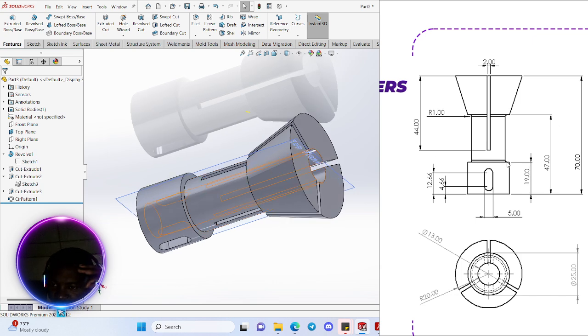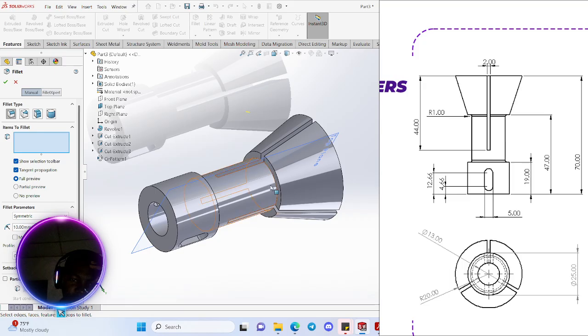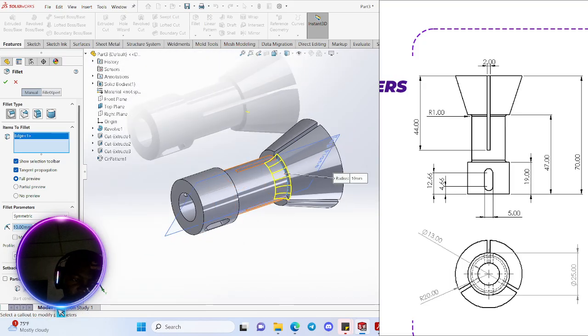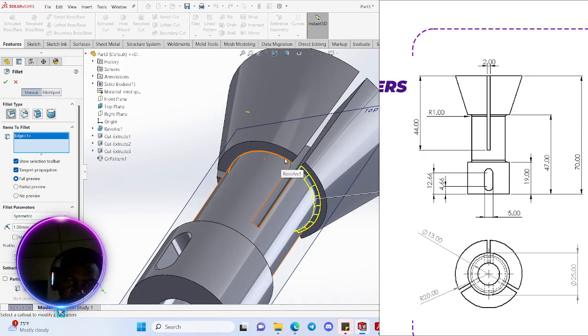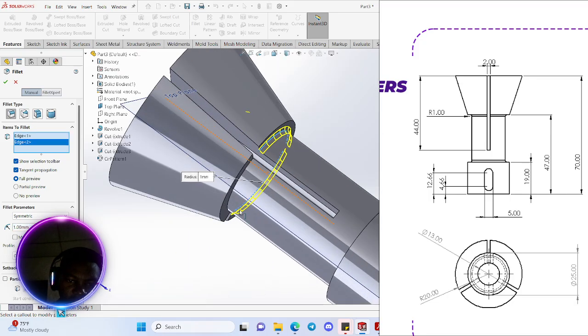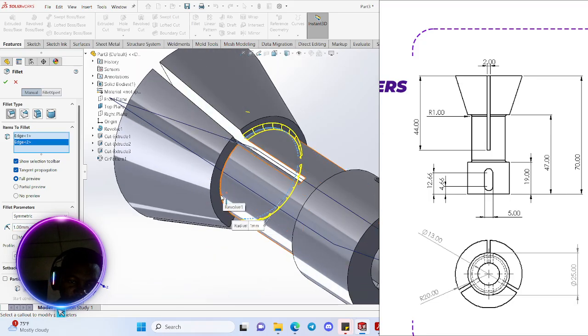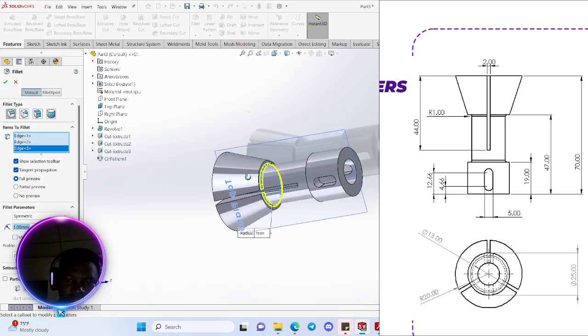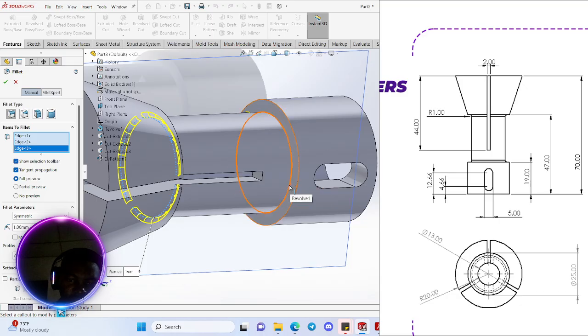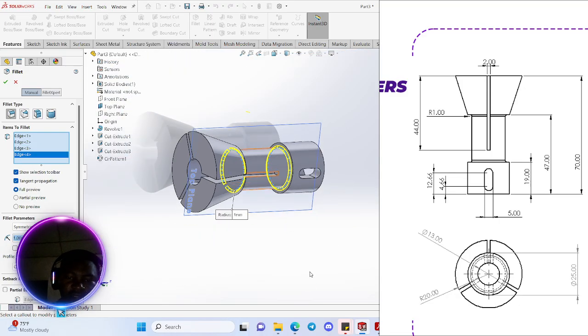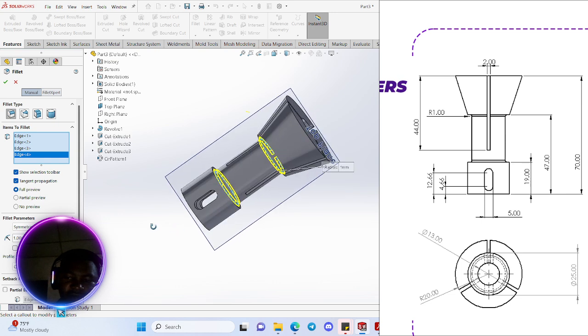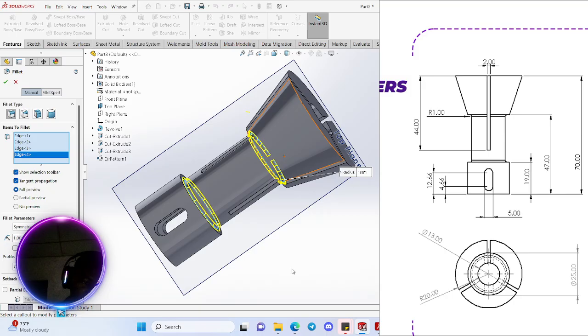But then look at something. The diameter here is 1 mm. Here is 1 mm as well. So that's your fillet. So you come here, select this. Please make sure it's 1 mm. You can likewise go to the other side and select it, and likewise the other side. So you've gotten this. Likewise come here and then select this. So with this you have your total diameters.